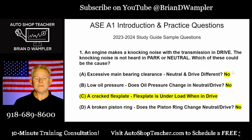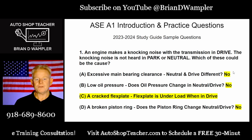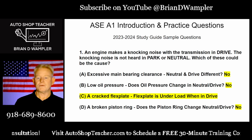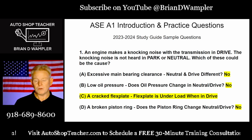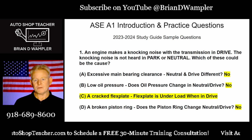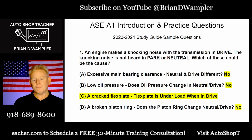So here's the quick answers on that. No, the main bearing clearance is not going to change. The oil pressure, if it's already low, putting it into drive... Yes, I understand there's an argument to be made that the engine RPM is going to be a little bit lower, so therefore oil pressure potentially a little bit lower, but not enough to make a knocking noise come and go. And then answer D, no, would be the answer.